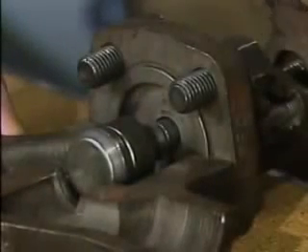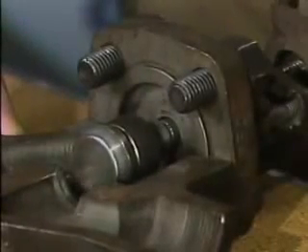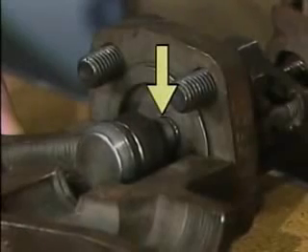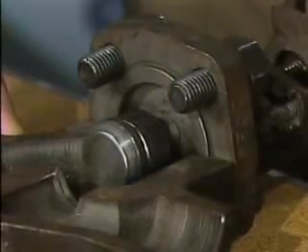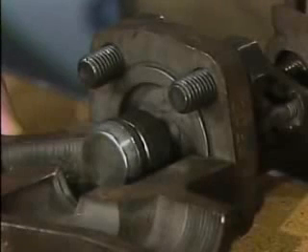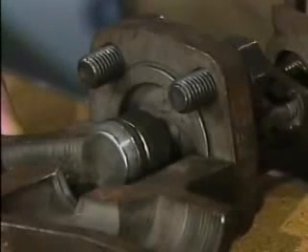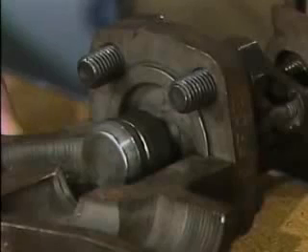Many globe valves, especially those used in steam systems, have a back seat that provides a seal between the stem and the bonnet of the valve. When the valve is fully open, the raised disc seats against the back seat. This prevents system pressure from building against the valve packing and keeps fluid from leaking into the upper part of the valve.